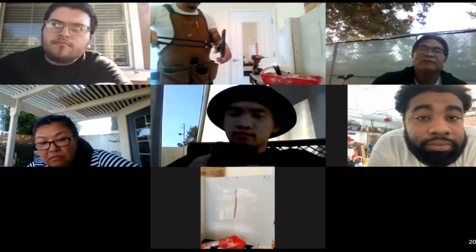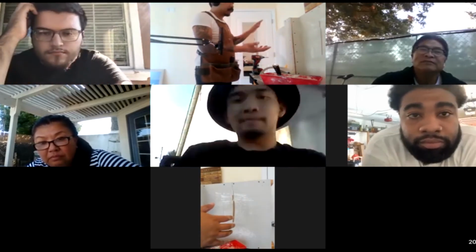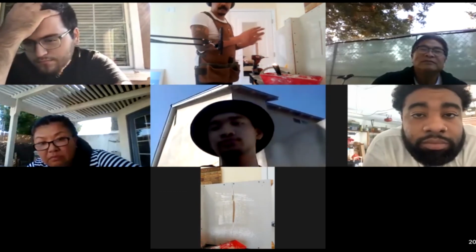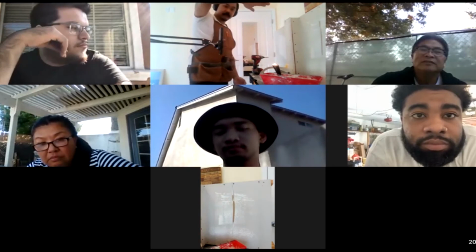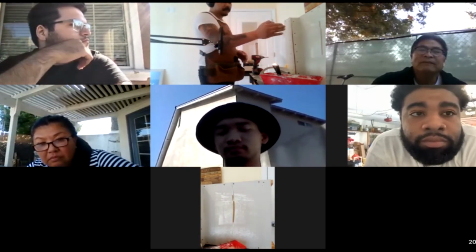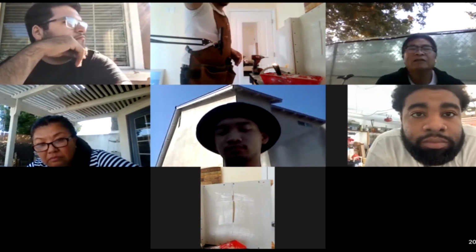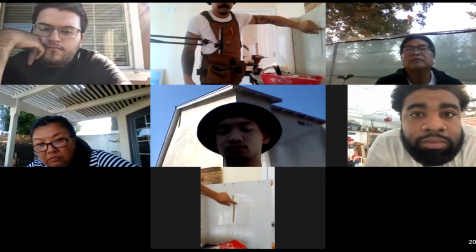So it's a standard 4x8. Each sheet will span 8 feet or 4 feet, depending on the orientation of where you put it. But usually you put it 8 feet long and then 4 feet in height, right? So once you pass the 8 feet, then you have another 8 feet to put next to it. So this represents the two sheets being put together, right?